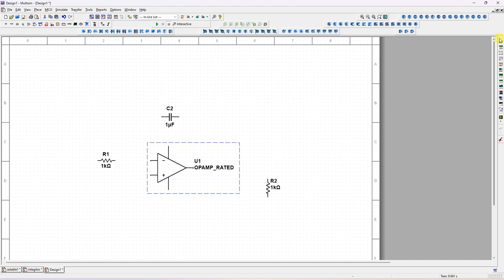Next, I want the function generator. It is available on the right-most side. One vertical menu is there. There, the first one is the multimeter, the second one is the function generator. You can select this. You can also give input using an AC source. I can go to place component, power sources, AC sources, and select and give it. Better to use the function generator.